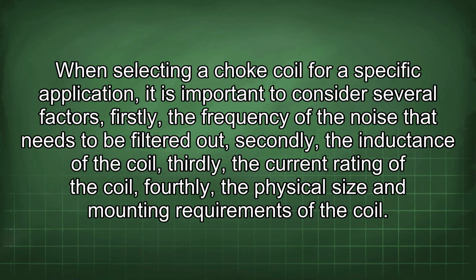When selecting a choke coil for a specific application, it is important to consider several factors. Firstly, the frequency of the noise that needs to be filtered out. Secondly, the inductance of the coil. Thirdly, the current rating of the coil. Fourthly, the physical size and mounting requirements of the coil.